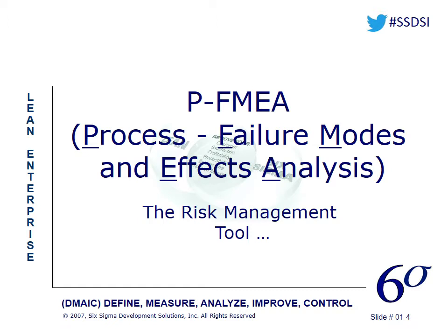Let's delve more into the FMEA, the failure modes effects analysis. You'll see here that we're specifically talking about what's called the PFMEA, or process FMEA. And this is the FMEA that is used within the Six Sigma DMAIC process: define, measure, analyze, improve, and control. This FMEA is really a reactive tool that morphs into a proactive tool, and we'll talk about how that morphing happens.